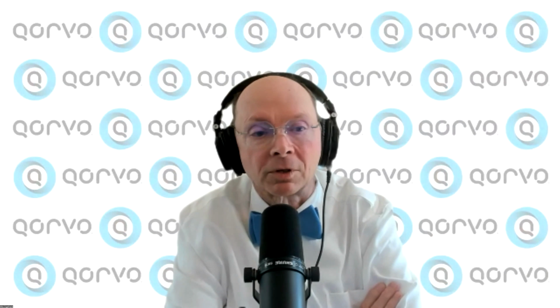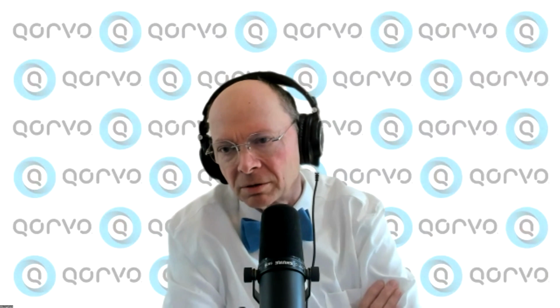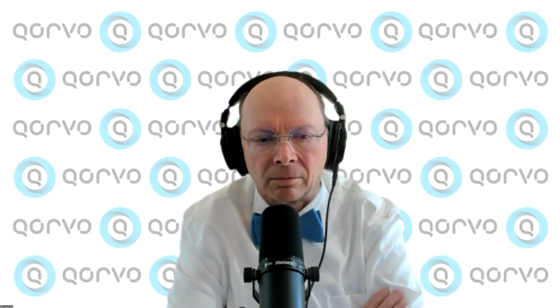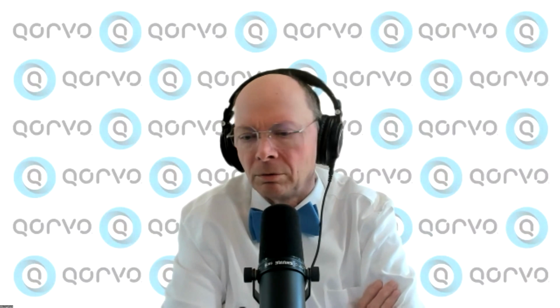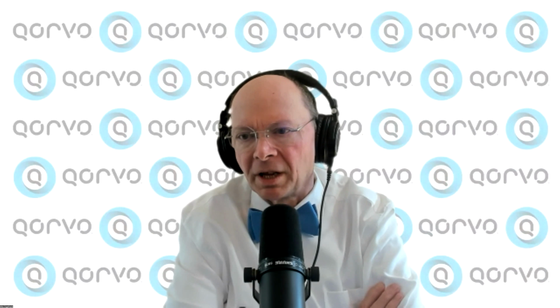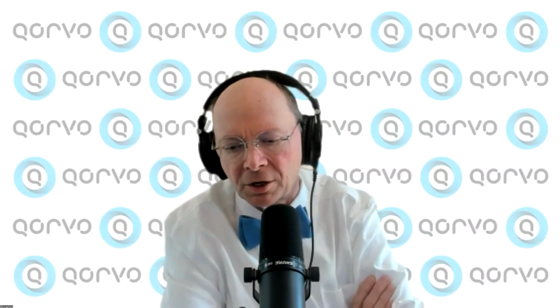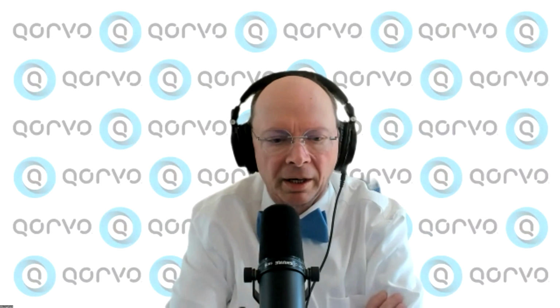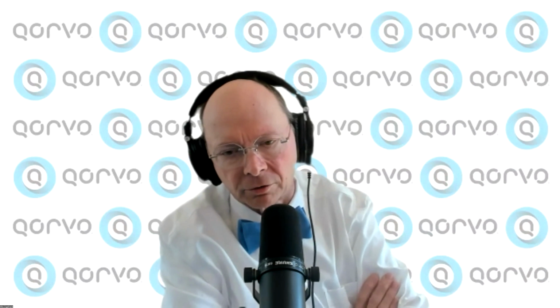Yeah. So the biggest thing that we're talking about now is the fact that you can make models from data sheets. That's huge. Yes, so these are for discrete devices. If you have a power MOSFET, there's a tool that will digitize the data sheet. The output characteristics. You put in the quantitative information about the RDS on, and it will make you a model that will match that RDS on and those output characteristics.